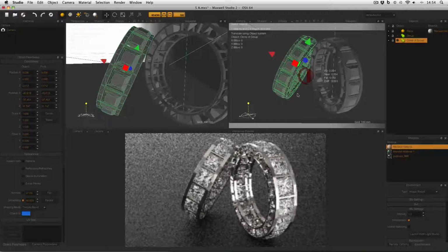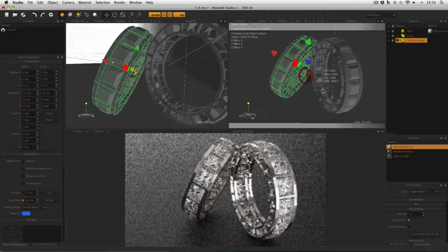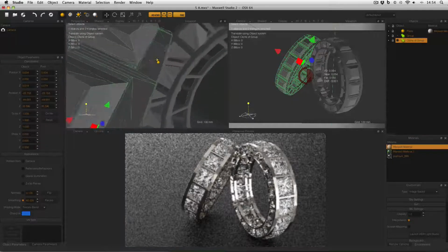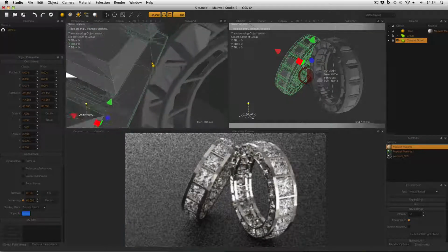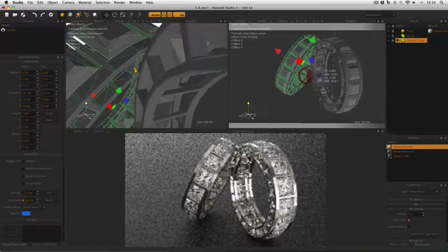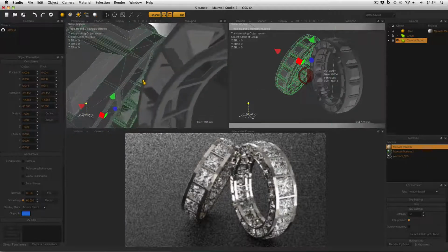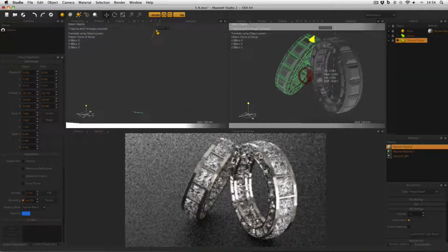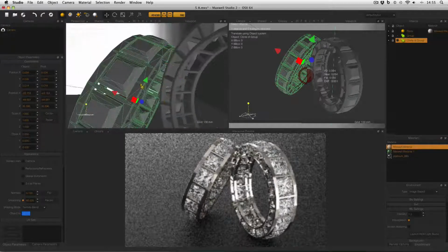And also I can see that the arrangement of the objects in the scene is what I would like in my render. For example, I might actually want to rotate this ring round a little bit more and then move it back into position. But I can use this view here to get a close eye on things and make sure that nothing is really intersecting very badly, and to make sure that there is maybe a tiny bit of intersection. Yep, that looks good. Maybe a bit too much, it's just touching there. But also definitely no gaps anywhere, particularly on the bottom. So I've got one viewport to do all of my close-in work and one viewport showing the overall scene.